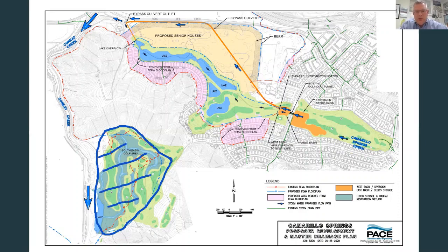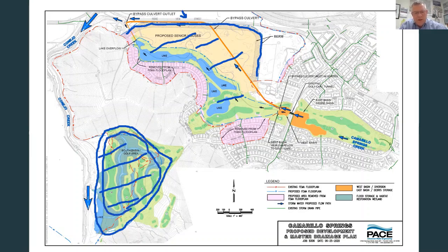Because when we build the berm, we've eliminated the Conejo Creek floodplain from being able to get past Ridgeview. And so we've taken some volume out of floodplain storage, and we needed to provide that back. The way we do that is to go into the South Golf area, which doesn't have houses around it, and we utilize the space in between the golf holes.